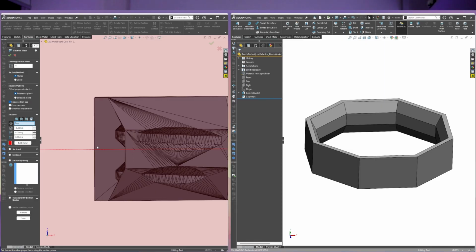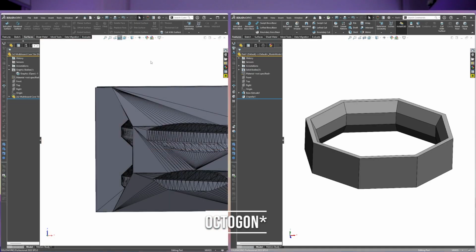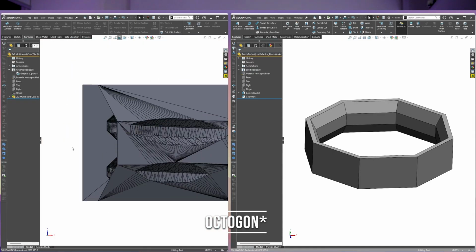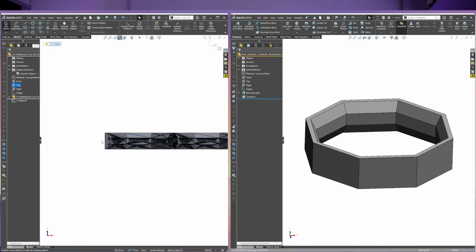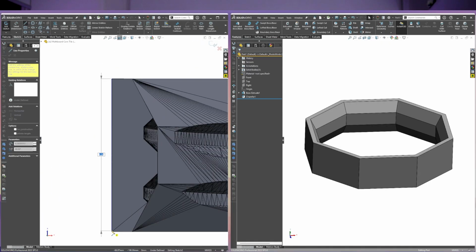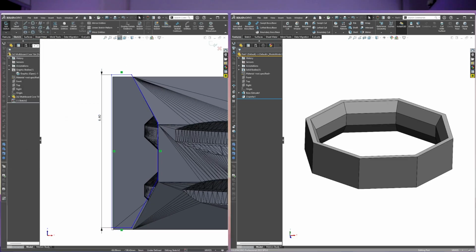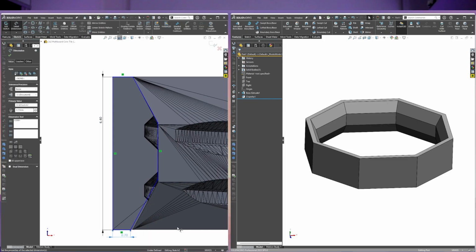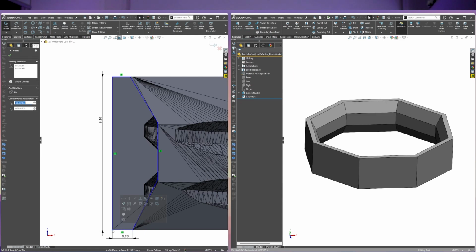I'm then using the SolidWorks tools, the basic geometry, in this case like a hexagon and chamfers, to create the first body of that model. Now we'll continue on with the video here. You could see that I measured the chamfer and then I just recreated the chamfer around each of the edges. And now my next step is I'm looking at those thread details, because those thread details, like if I'm 3D printing based on these files, I need them to be super accurate.